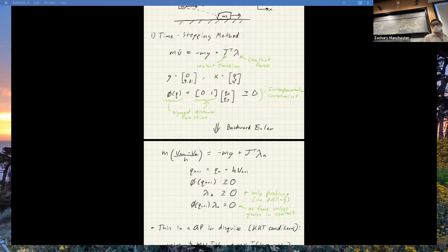There's a few ways to think about this. One is that these dynamics are inherently non-smooth, right? And these impact events are doing discontinuous things. So in some sense, approximating the trajectory over a time step using a smooth high order spline is a bad approximation when you hit one of these discontinuities, right? Trying to fit that cubic spline from RK4, say, to this giant impact event doesn't work very well. So that's one way to think about it.